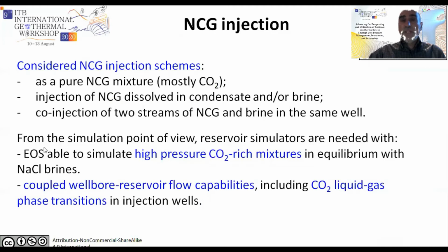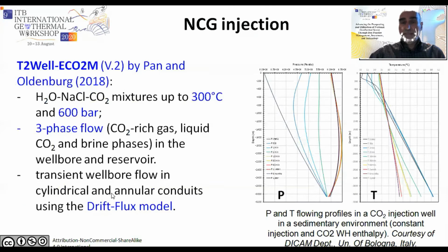So from the simulation point of view, reservoir simulators are needed with equation of state module able to simulate high-pressure CO2-rich mixtures in equilibrium with sodium chloride brine, and coupled wellbore reservoir flow capabilities, which include CO2 liquid gas phase transition in injection wells. An example is T2Well/ECO2M.